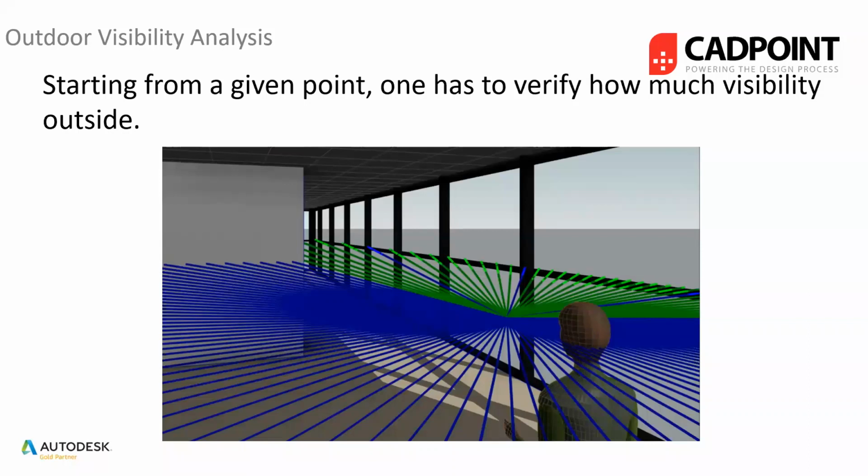This is a 3D view from within Revit, taken from the height a person is sitting in their chair, from their eye level. And you can change that height to be whatever you want. Starting from a given point, it will calculate how much visibility we can see from our particular chair or where we're sitting. You can see every green line that is shooting out. As soon as a line hits an obstacle, it will automatically turn blue. So if I place this as a blank panel with no glazing, all of these lines are going to turn blue. If I move this post, this line is going to turn green. And you might ask, well, what can you do with all of these lines?